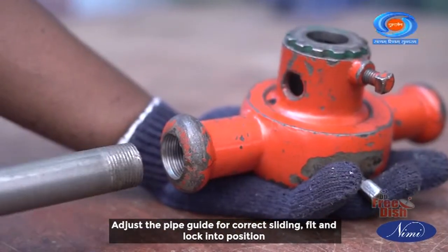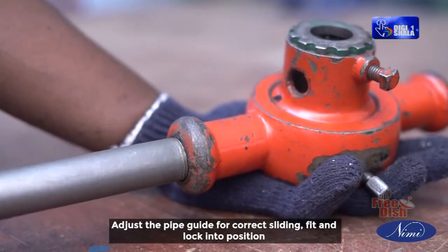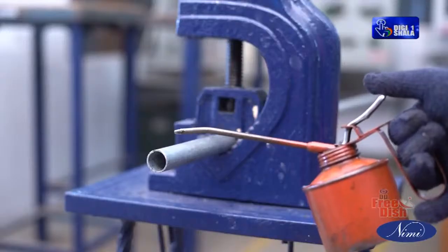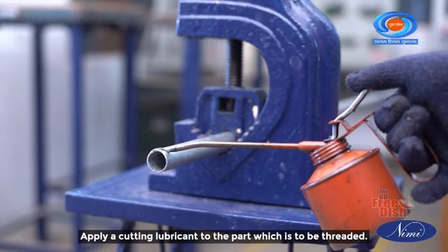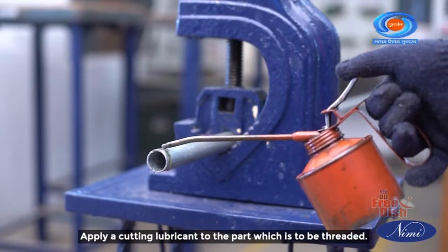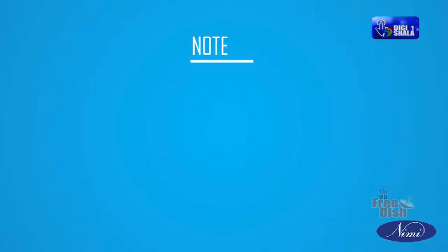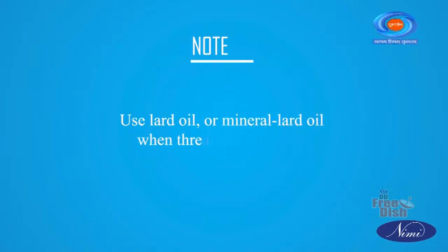Adjust the pipe guide for correct sliding fit, and lock into position. Apply a cutting lubricant to the part which is to be threaded. Note: use lard oil or mineral lard oil when threading GI pipes.